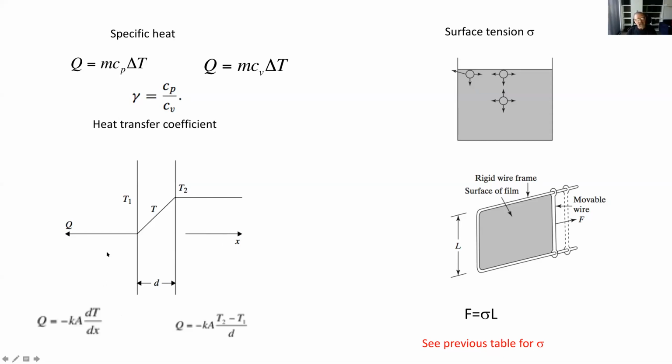So now, how much heat am I losing through the wall? This type of calculation is good for people who design air conditioning. A is going to be the area of the surface, and it is going to be this K, which is the property, the heat transfer coefficient, and then the change of the temperature along this D. We assume again that the temperature change is linear, and if K is constant, it is linear. If I translate that equation, which is called the Fourier equation, very similar to what we did before, it looks like this: minus K, A is the area here, the gradient is T2 minus T1 divided by D, the thickness of the wall.